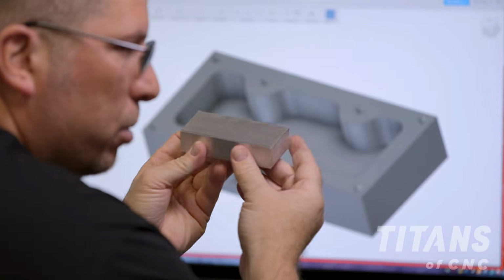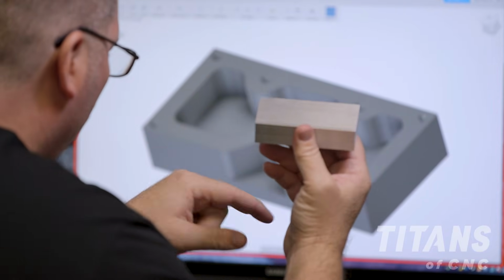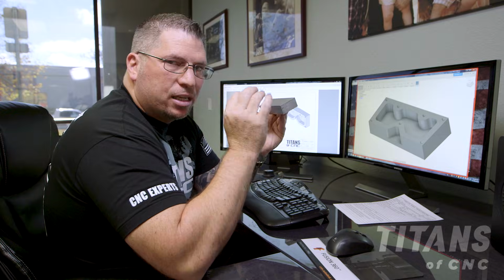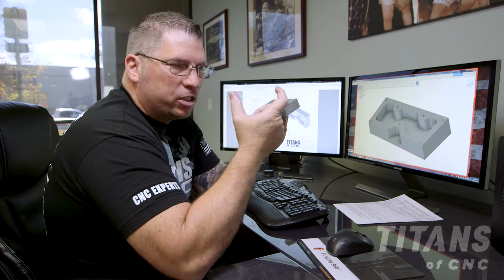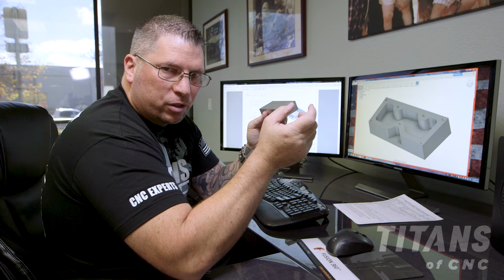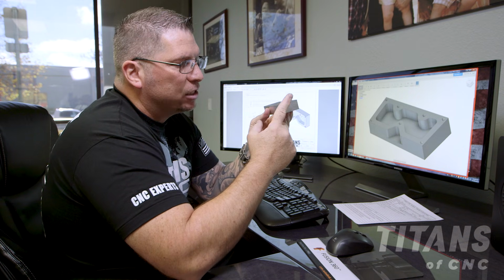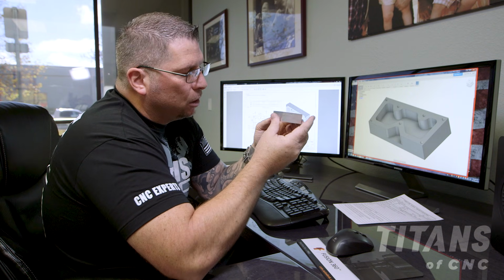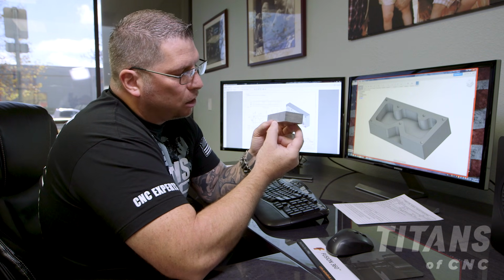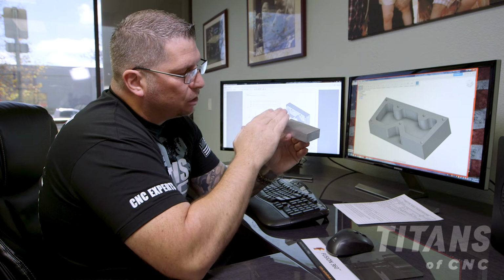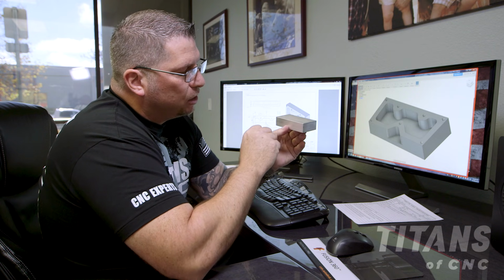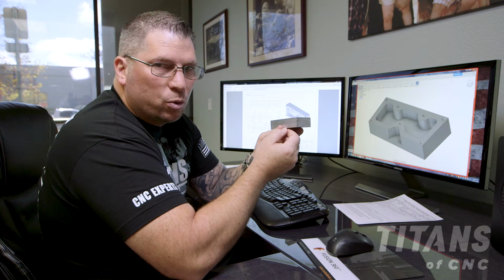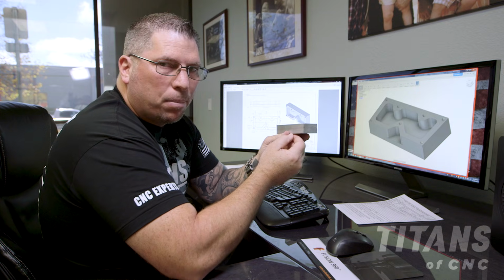We saw cut the material, which you can see on your setup sheet at 4.1. And because the finished part is 4 inches, that leaves us an extra 100 thousandths divided in half. That's 50 thousandths on this side and 50 thousandths on this side. We add a 1/4 inch on the bottom, but I need some material to take off the top. So I'm basically going to skim 20 thousandths off the top, which will leave 230 thousandths at the bottom.